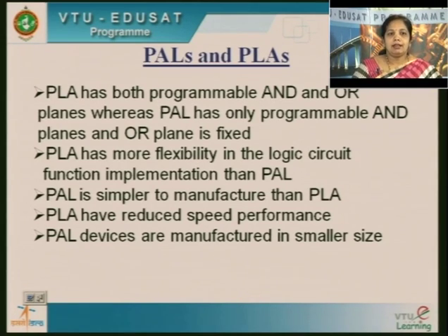So PAL is simpler to manufacture than PLA because of course the OR plane is fixed, so that's why it is simpler. PLA has reduced speed performance, since you are programming both the planes, the speed matters over here. PAL devices are manufactured in smaller size compared to PLA.